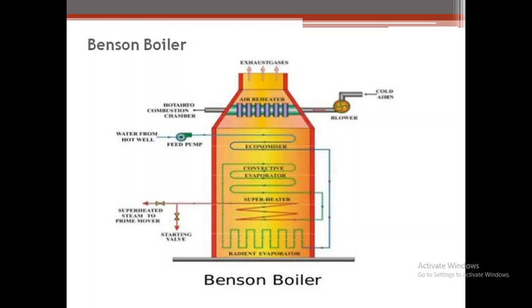As it has no drum, for this reason it is lighter than other boilers. Next, its starting time is less compared to the other boilers, and it has up to 90% thermal efficiency. These are the advantages of this Benson boiler.